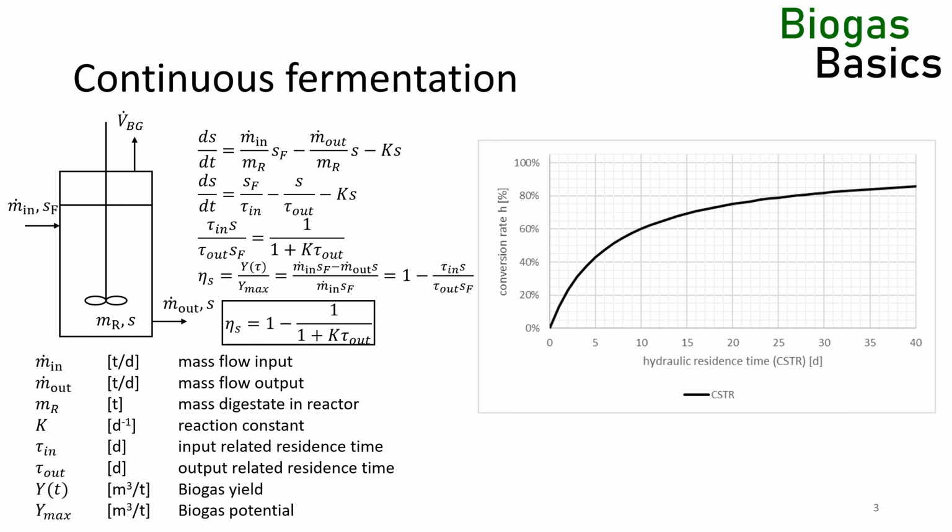The reaction in our first order model is substrate plus water reacts to biogas, but the correct reaction is substrate plus water reacts to biogas and biomass, and the reaction itself is catalyzed by biomass. The first order model does not model the biomass. It merely assumes that enough biomass is in the background to ensure that the reaction can progress.